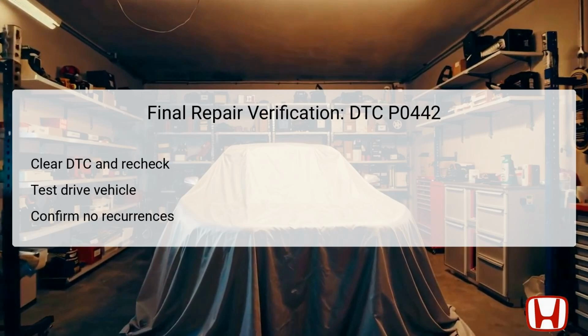Once all troubleshooting steps have been performed, including necessary repairs or parts replacements, the final repair verification process must be completed. Start by clearing the DTC using the diagnostic tool, which resets the trouble codes stored in the PCM. Following this, it is crucial to take the vehicle for a test drive to monitor the performance of the emission system under operational conditions. Check for any illumination of the check engine light or reappearance of DTC P0442. Ensuring that the DTC does not reoccur indicates that the repair was successful and that the emission system is now